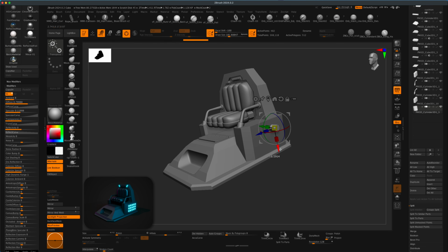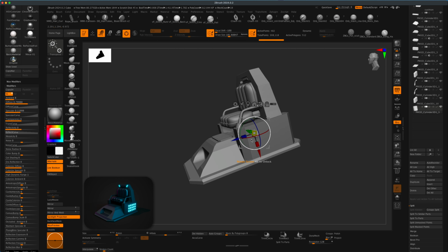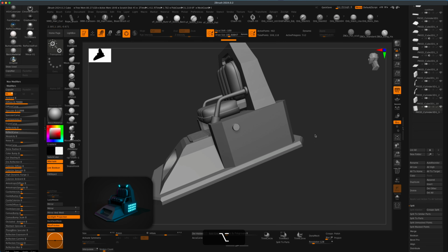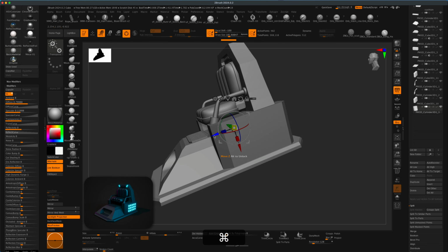And I just wanna punch some holes for additional design on the side here. So let me put the cylinder right in here. Something like that I think is pretty great. We can decide what size we want. Maybe something like this should work. Holding down the control key, I'm going to start dragging, release control and just do a few of them. Control and drag to get rid of the mask. Hold on control and bring it down, and then release control to do another one. Control and drag to get rid of it, and then click on this button to punch the holes through.